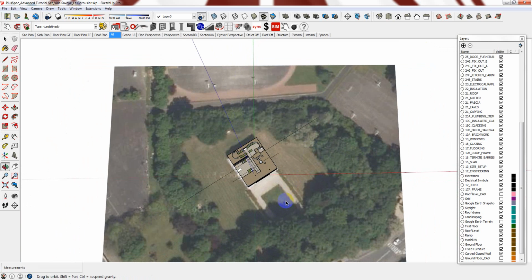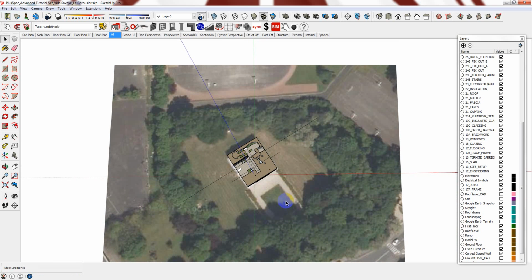The main thing is, do not actually have your master file or your working file that you've rotated off axes. If you have done it, you're better off to try and bring it back off the site, rotate everything. You're going to have to explode it. So just get in the habit from the outset, knowing never work off axes.